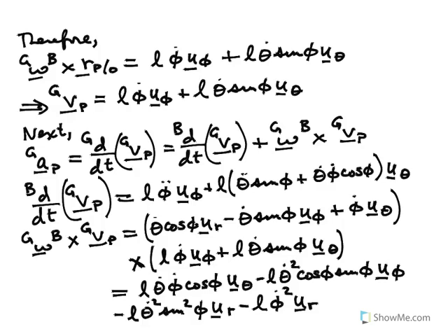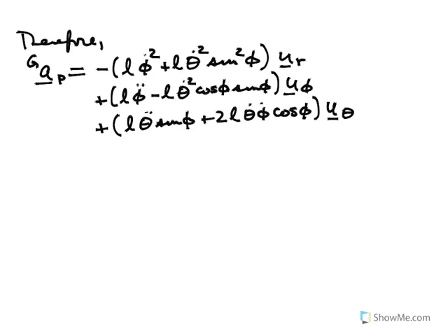And you can see that, in both cases, both the first example and the second example, we expressed the position in terms of coordinates that are fixed in the second rotating frame, and then we applied the transport theorem from that second rotating frame to the first frame, which is the base reference frame, which was the ground, to get both velocity and acceleration as viewed by an observer fixed to the ground.